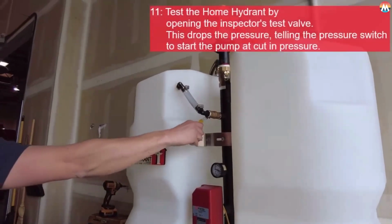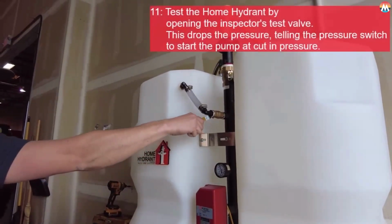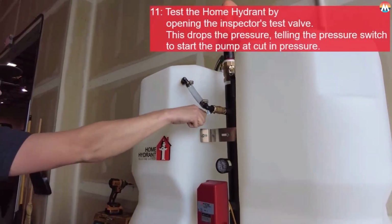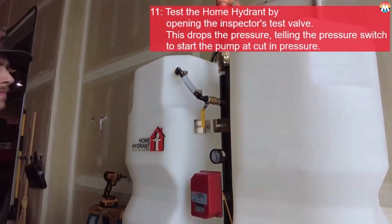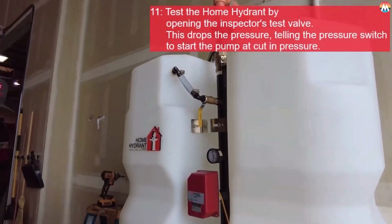The last step to the home hydrant installation is testing the home hydrant. After the timer has timed out, we're going to open the inspector's test valve, dropping the pressure, starting the pump, and testing the flow switch if it is installed.